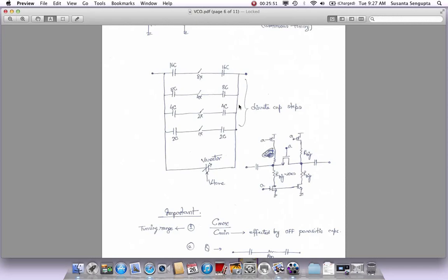What I have here is a simple picture showing how we implement the switches. These are normally NMOS switches. So here is the switch, maybe not one, maybe two of them back to back, with source drain here, or the other one could be the source drain here, and they could be in parallel. But what we are trying to do is, if you put two caps here this way, the DC here is floating. So this switch doesn't know what the DC value is here, it's floating. So what we tend to do is put some big resistors, maybe say 20K, 50K, whatever works for you. When this switch is on, these nodes will be pulled down to ground. So the potential at this point and this point, weakly, by these weak devices, will be at ground. So when they're at ground, you get the maximum VGS to turn on the switch,